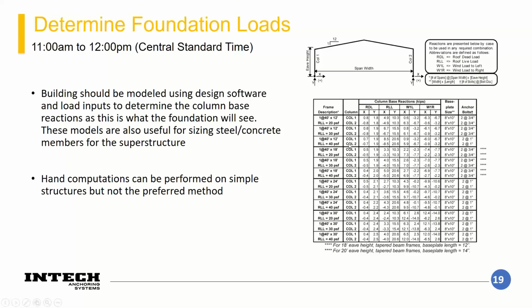So understanding how all these loads end up right here at the foundation level is going to be the most critical. And whenever you're doing simple structures, you can do this by hand pretty easily. But as your structures get more complex or your load cases get more complex, it's probably better to use some type of computer modeling approach to determine what these loads are going to be.